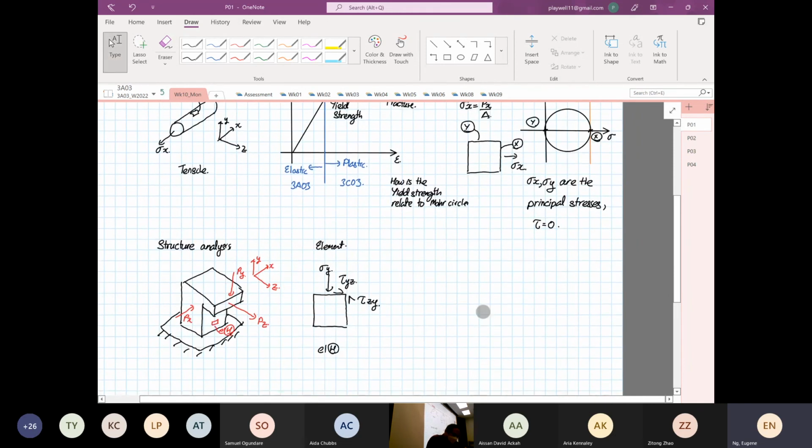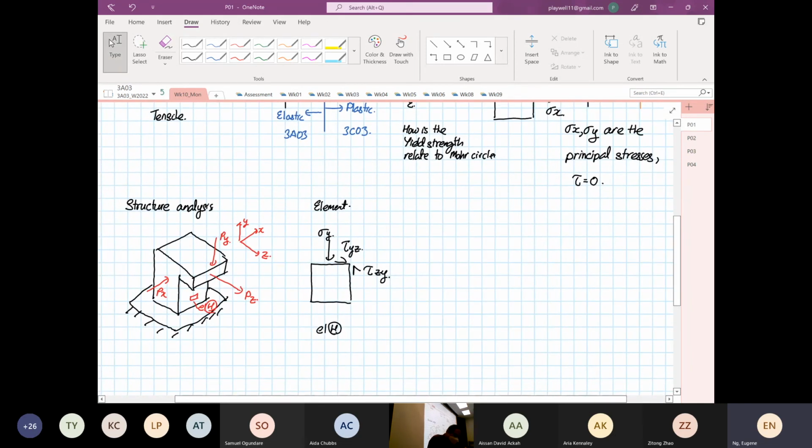Okay, already based on the formula, we can see that stress X, stress Y is equal to Py over A plus or minus Mx over Ix multiplied by z, and then plus or minus Mz over Izz multiplied by x.